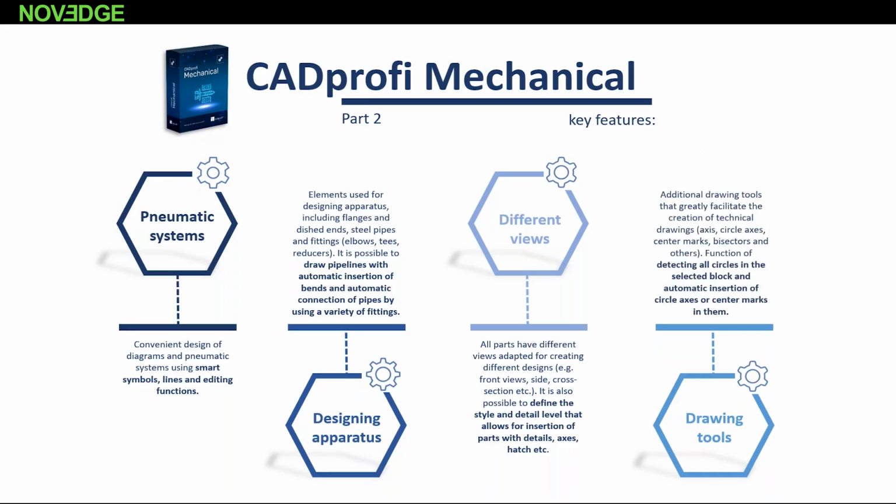We have also drawing tools in CADprofi Mechanical. That's the additional drawing tool that greatly facilitates the creation of technical drawings. This function detects all circles in the selected block and automatically inserts circle axes or center marks in them.